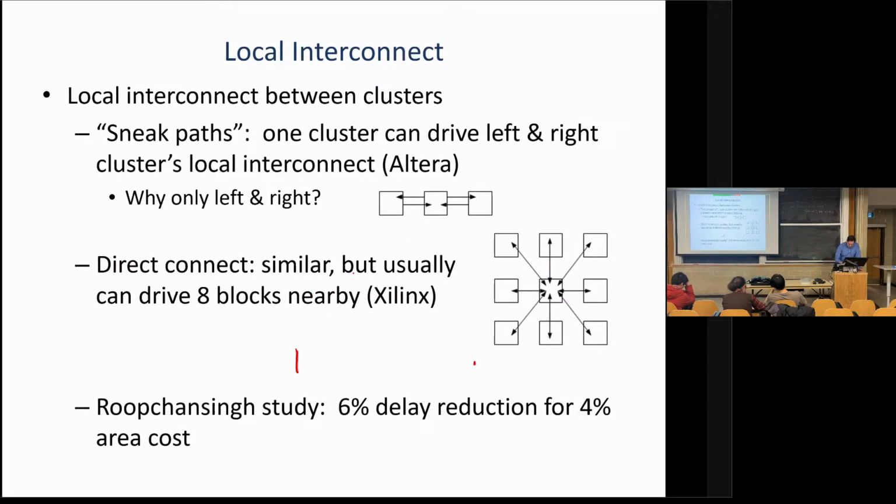And if you were to make this structure in an Intel architecture, so these ones are fine, right? These are horizontal connections. If this row is broken and you shift up by 1, they all still work. You don't need to do anything special. If you have a vertical direct connect like this that goes up 1 row, in an Intel architecture, you would also have to actually make that wire go 2 rows up. Okay, but the whole reason you made this wire was really short. You were going straight into the local interconnect of that one above you. Hopefully you were going from the top of this block to the bottom of that. Because of this need to be able to skip over a row, you'd have to go an entire block above that still.